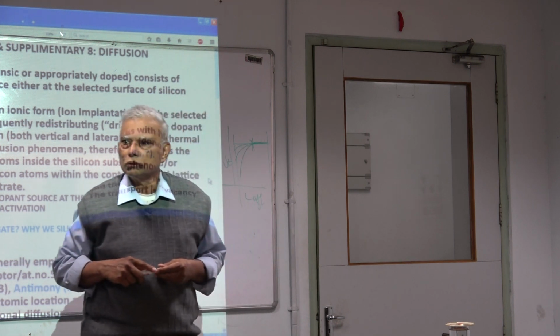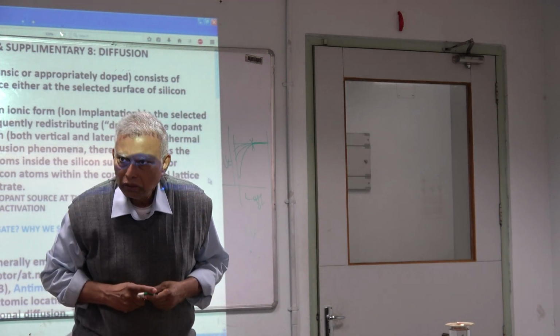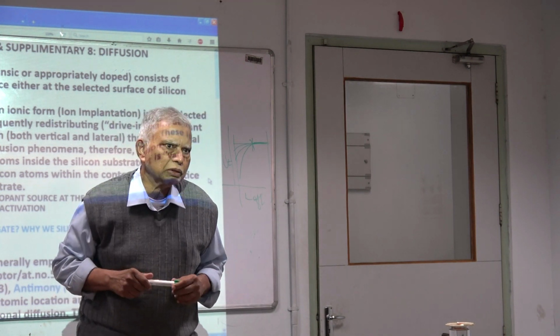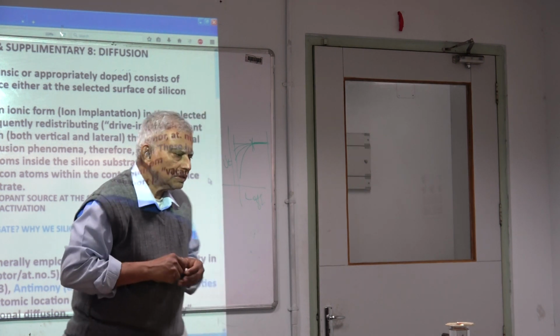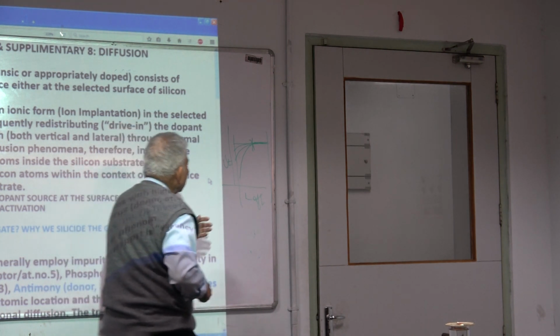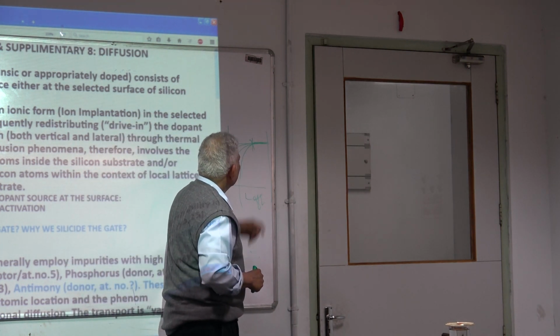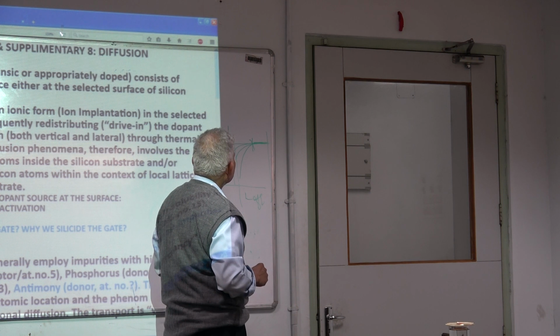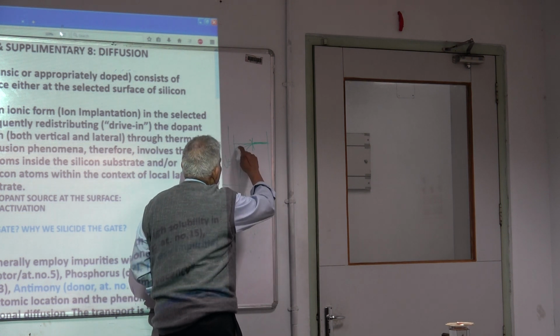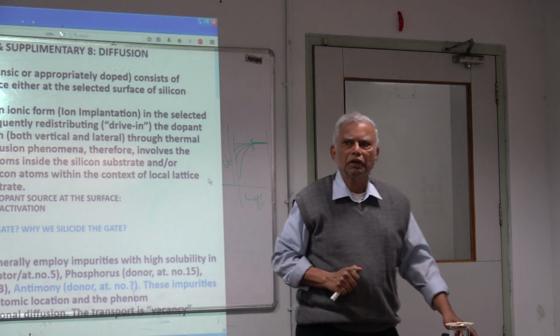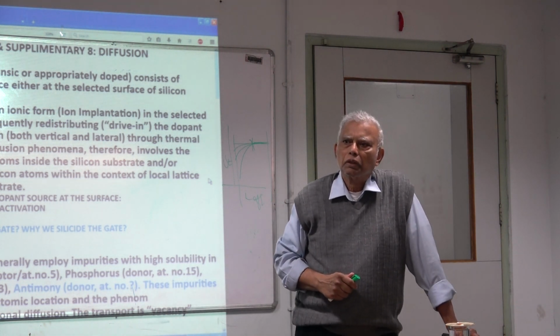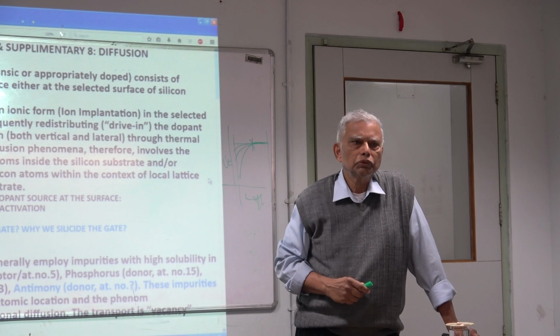How you control the short channel effect is the most important parameter in scaling the devices. So please be intimately familiar with that, and recognize that you as a device designer are rated by how well you put the process together to improve short channel effects.